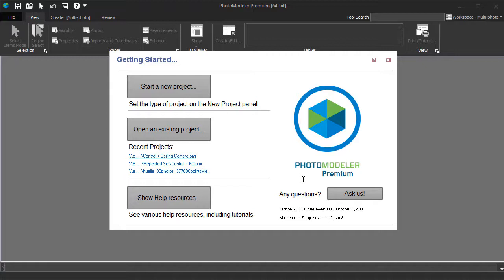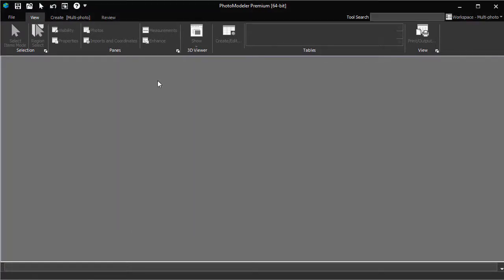See the separate single sheet calibration tutorial. If your object is larger than a foot, you should use the multi-sheet calibration outlined here. To fine-tune the camera parameters for projects of any size, see the field calibration tutorial.